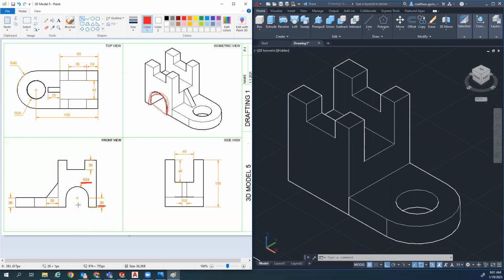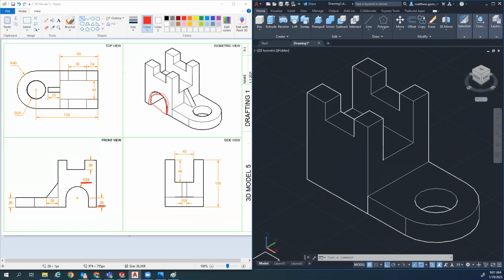I can assume that this happens in the center of the box. So that kind of makes it easy. So I think that's all the measurement I need. I'm going to draw a line, hover on this face, find the midpoint down there. I'm going to go up 20. And then I'm going to draw a circle.